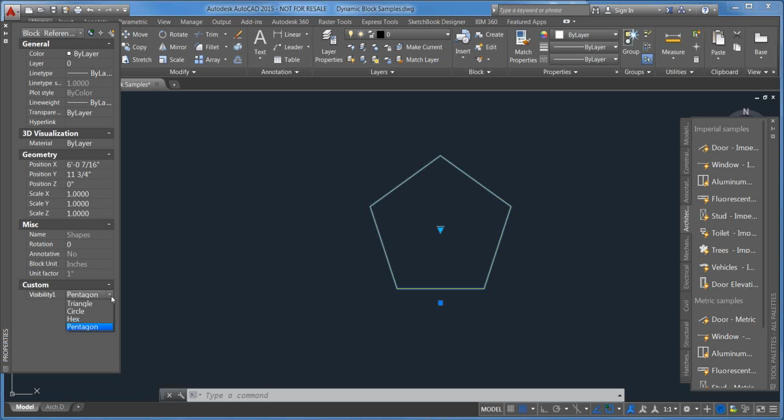I'd need a little bit more information to know exactly what the desired goal is, but there's not really a way to push data, not in basic AutoCAD anyway. Perhaps in Map and things like that there are a lot more advanced information management tools. In basic AutoCAD, the attributes are pretty much push only, or well, they can read data and report data if you use fields and things like that.